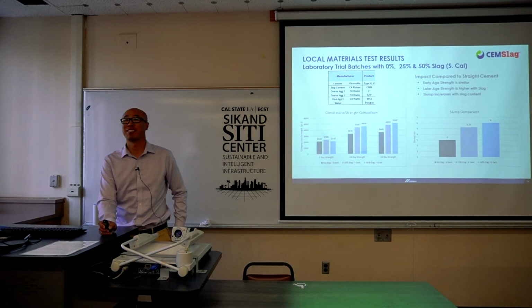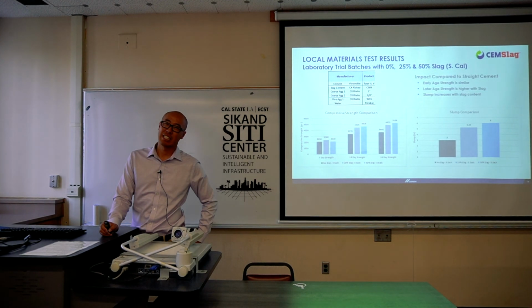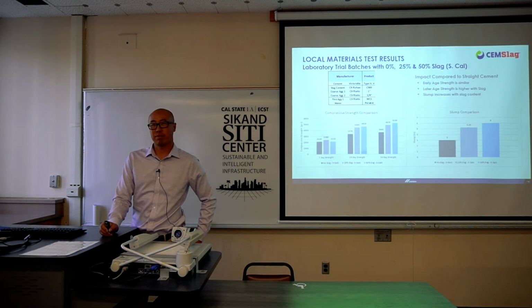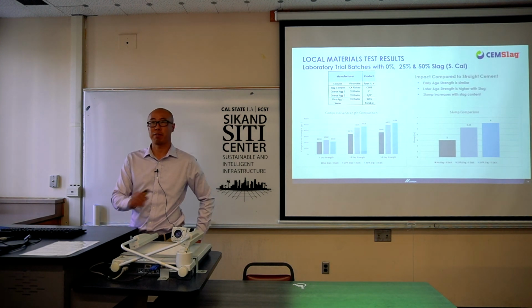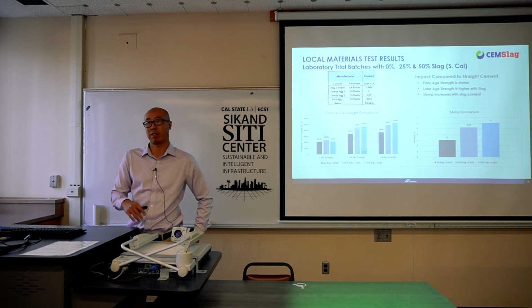Thank you. Yeah, sure. I was wondering if the curing is also the same as regular concrete using fly ash or Portland cement. As a concrete contractor, you have to be very disciplined in the curing process. No matter whether you use fly ash or slag, you have to make sure there's moisture in your concrete to ensure those chemical reactions take place.